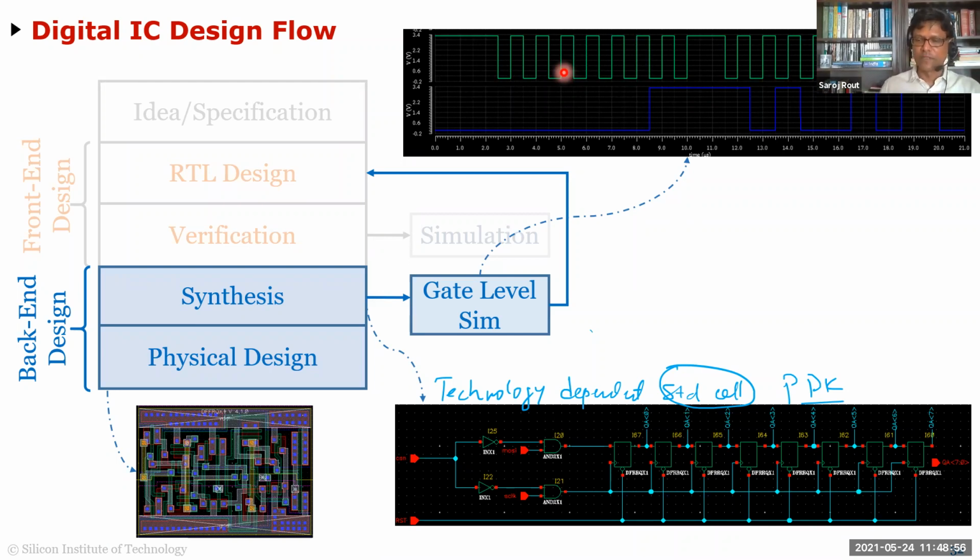I personally have always worked in the analog domain, so we just do layout. I have never used place and route tools or clock tree synthesis. But for people doing digital design of any significant complexity, there are certain tools. Same thing with front-end design. If your front-end design is as simple as just doing Verilog and a very simple synthesis, then the tools are very simple. If the synthesis is very complex, then the tools also get complex, and some will do partitioning first, and what's called pre-synthesis timing, before that.